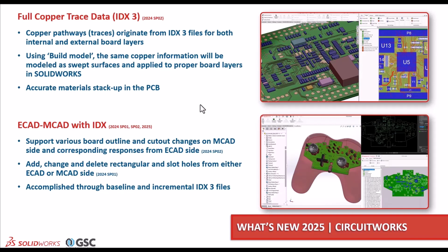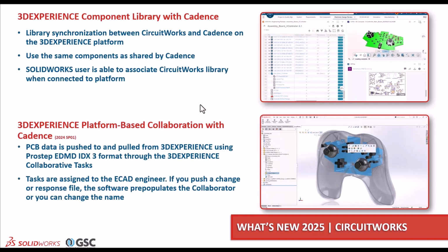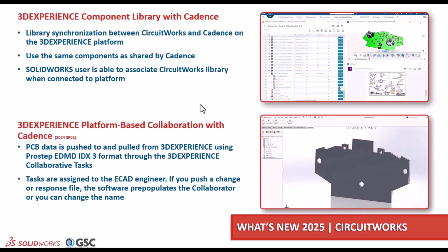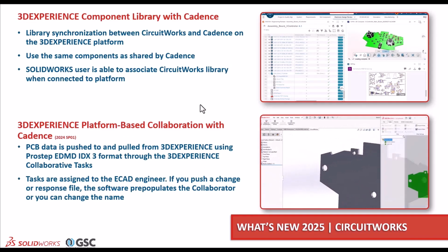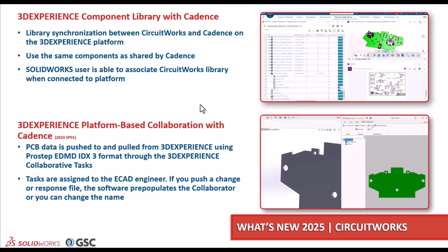You're also going to see, if you're on the Cadence Allegro design platform, integration with SolidWorks. If you're considering PCB design tools, this might be a valid tiebreaker. The integration is smooth and seamless, as a push-pull mechanism allows board changes to propel back and forth. We'll talk about some of the finer granular details of that as we continue. The vehicle for that is the CircuitWorks program, so that's one of the reasons it was included in the SolidWorks Standard installation.